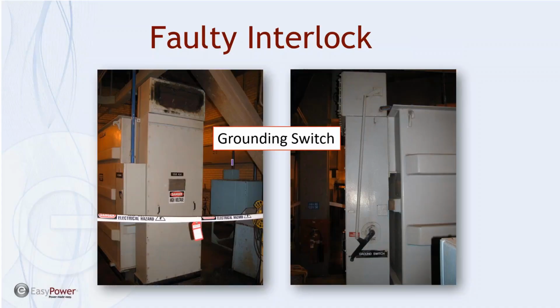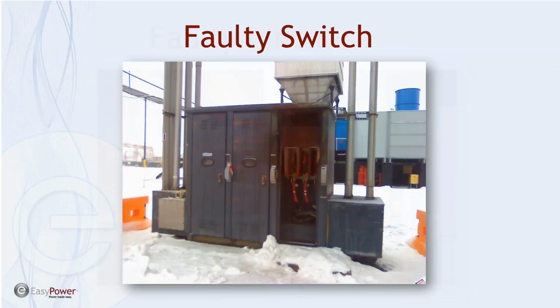They have these little square things with a flag that you can stick on with a little square magnet, and it just tells you what you're working on when you have look-alike equipment, which is always a good idea. But also, if you go away and you're going to be doing something after lunch, have another job briefing to determine what happened and where you are.